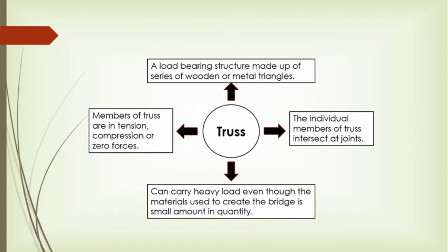The individual members of a truss intersect at joints. The most interesting part of a truss is that it can carry heavy loads even though the amount of material used to create the bridge is small. When a load is applied, the members of a truss experience tension, compression, or even zero forces.